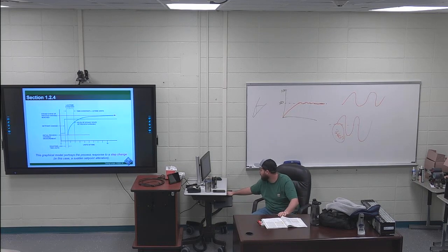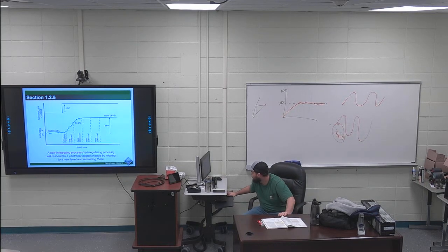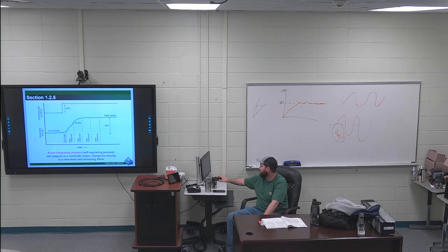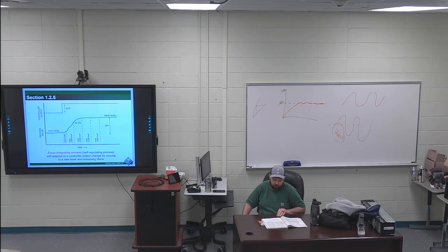So you can see, like this right here, your time constants in order to reach your new level. Controller output, this is just the change in controller output. So this just might be turning on and off something, maybe turning on a heater, and then this is measuring your temperature in a tank or vessel or something like that. So this says turn your heater on. How long does it take for me to get up there? 5 time constants or whatever, based on what you're trying to do. Temperature takes a little bit longer for stuff to react.